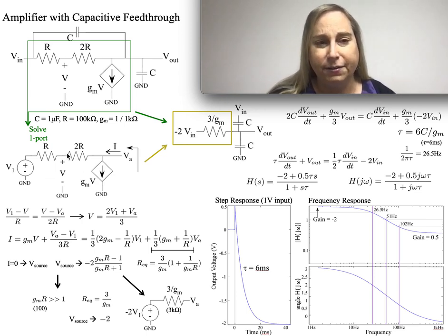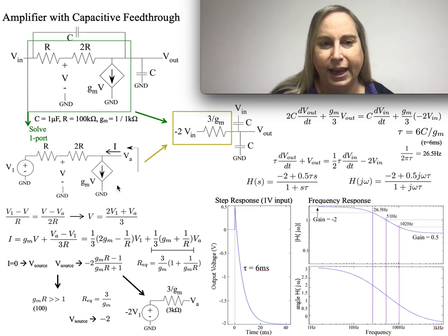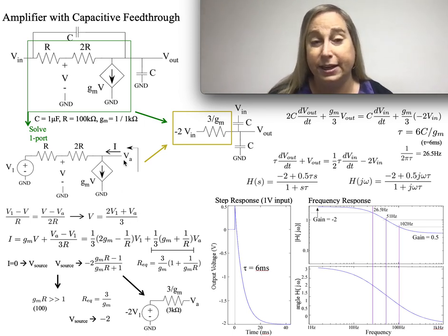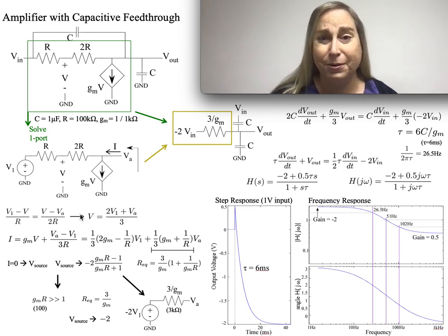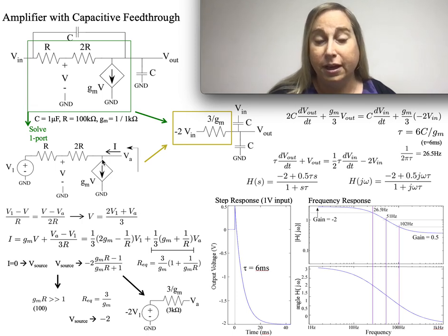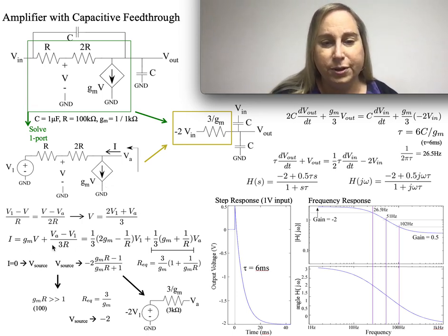Usually the easy way to handle this is to say I can deal with KCL at this node, which gives me this equation for V in terms of V1 and VA. VA is the port voltage at that node. And from that, I can take it one step further and ask what's the current, which is again a form of KCL at this node, which is going to be both the voltage controlled current source and the sum of the resistance chains. And then you do a little bit of algebra, and you get both of these